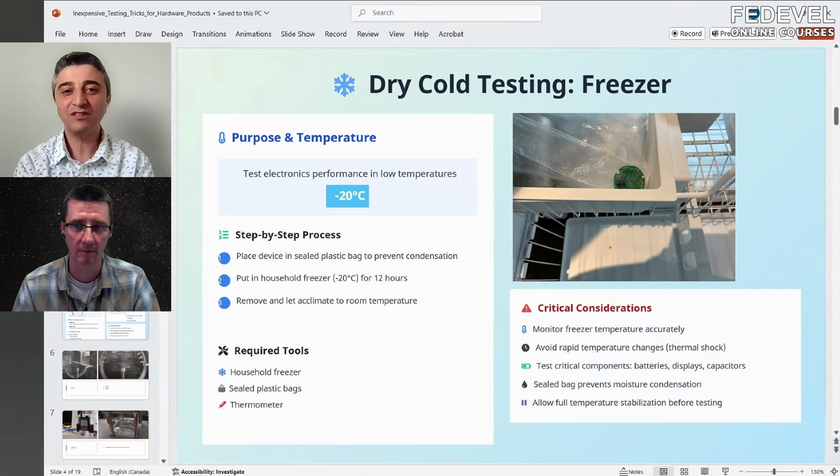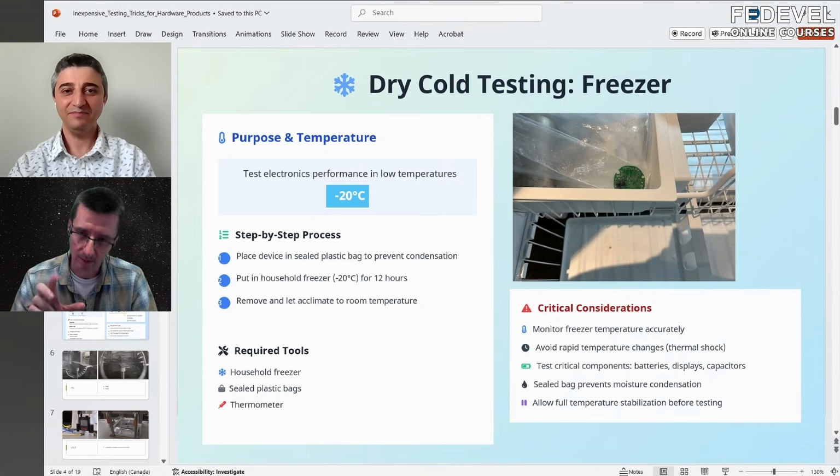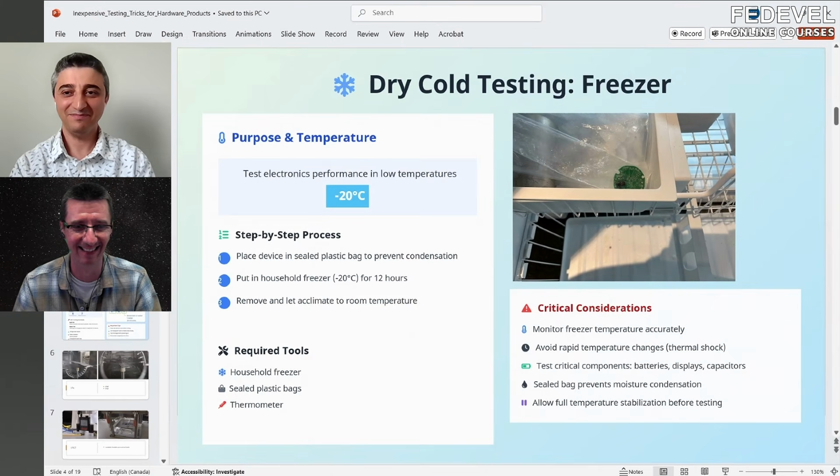Now you can go and focus on where the issue is. Yeah, and also for testing and debugging, when trying to fix the problem, it's easier: you maybe change your code or change the register settings, you run it again, you use the freezer spray and see, okay, it didn't fix it.